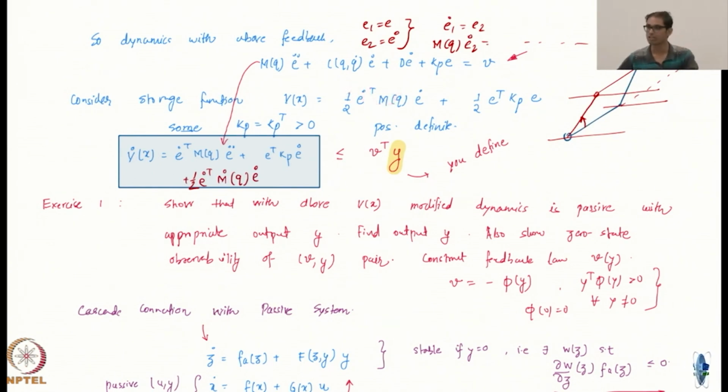Now think of inertia. If I want to write the inertia in a fixed frame, you have to choose some frame to write the inertia. If I choose to write the inertia in this frame, then this will be fixed. Well, this will also not be fixed actually, because as this moves, there is a problem. Suppose I choose this frame to write my inertia, the rotating frame, but then this guy is still rotating with respect to that frame. So if your object is moving in the frame, then the inertia is changing, right?